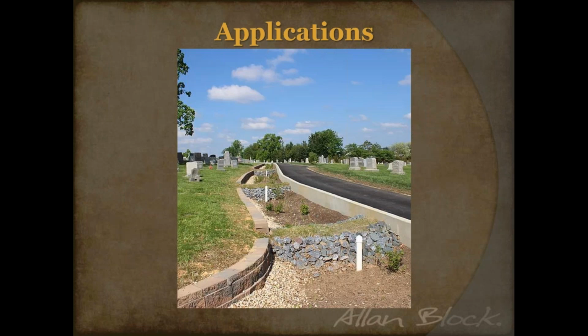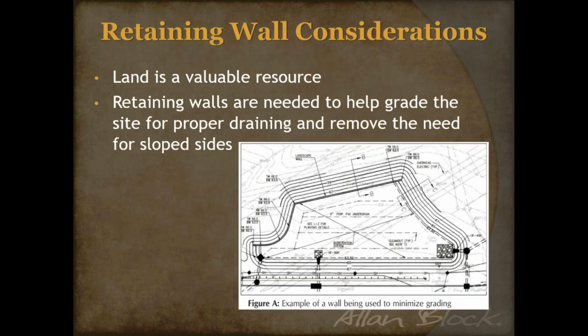And that's kind of where my transition's coming in. That's where we see retaining walls. For example, here, this was just a site plan that was in our office. We know there's going to be some type of detention or bioretention pond here. And so they're using a retaining wall on one side so they don't have to have the entire slope. By limiting the entire slope, they keep the capacity where they need to handle that stormwater. And so it's a balancing act.